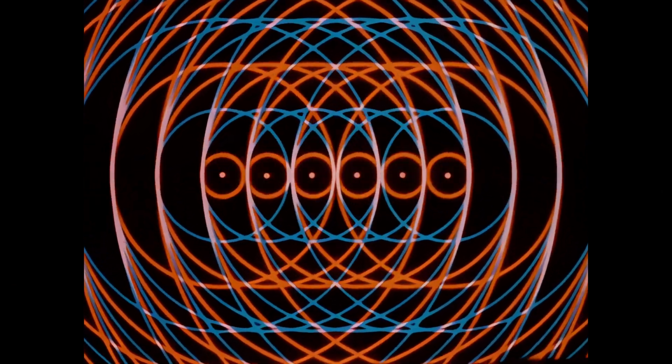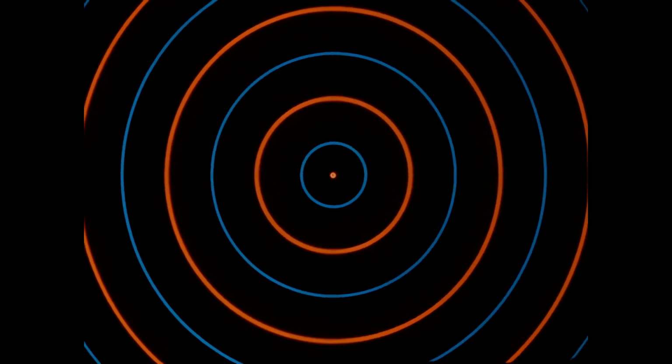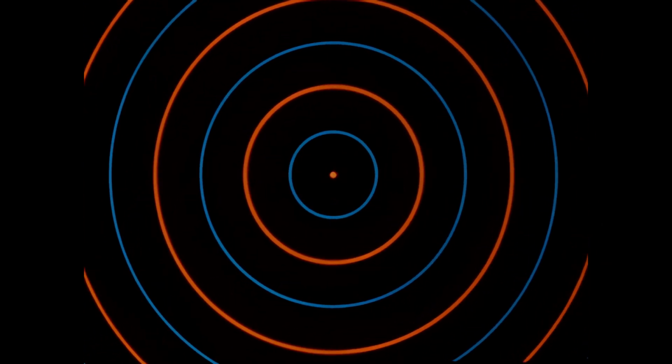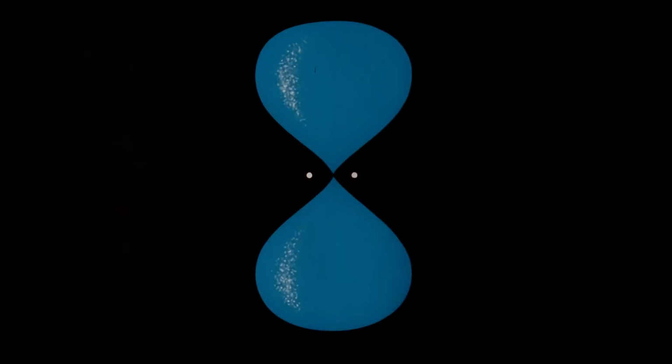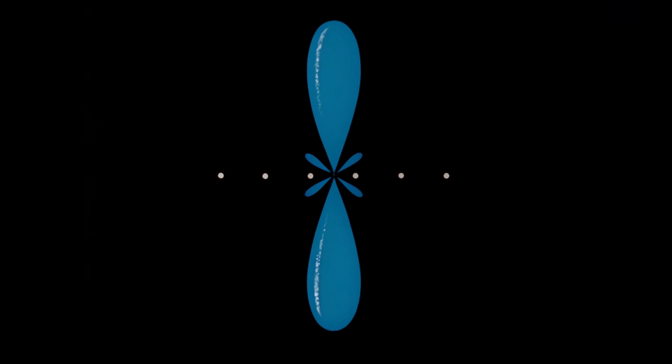Let's now review how bidirectivity is achieved. A single dipole with its omnidirectional radiation pattern produces a donut-shaped polar diagram. By adding a second dipole, half a wavelength from the first, we have altered this polar diagram to produce two lobes. By increasing the number of dipoles, we have sharpened these lobes. To aid this presentation, the antenna size in relation to the polar diagram is greatly exaggerated.